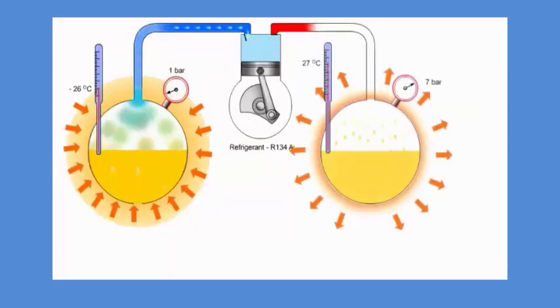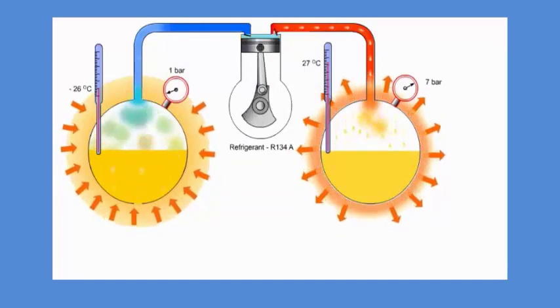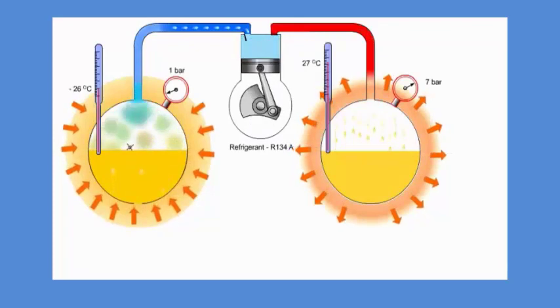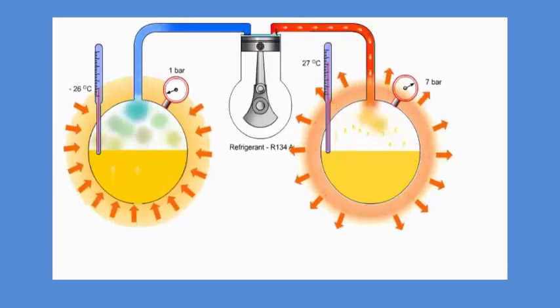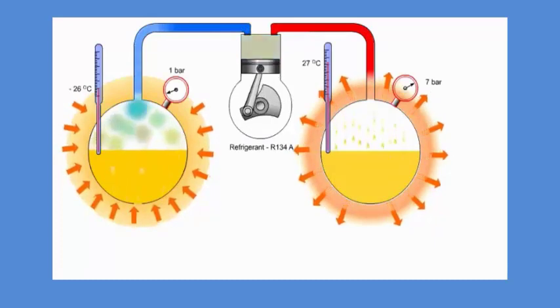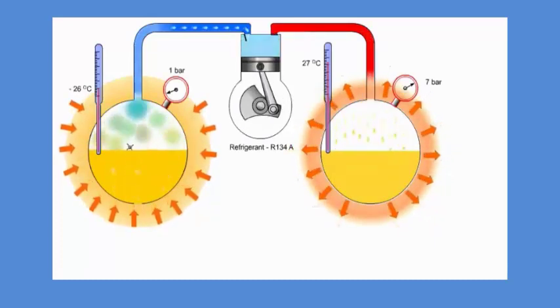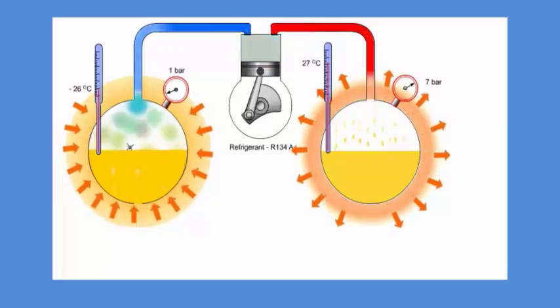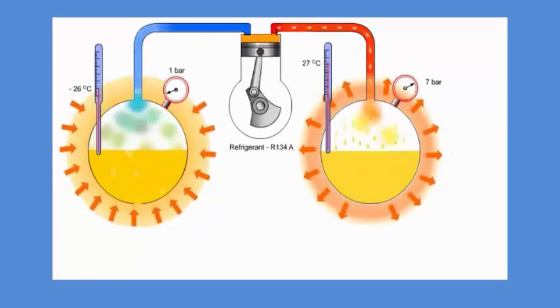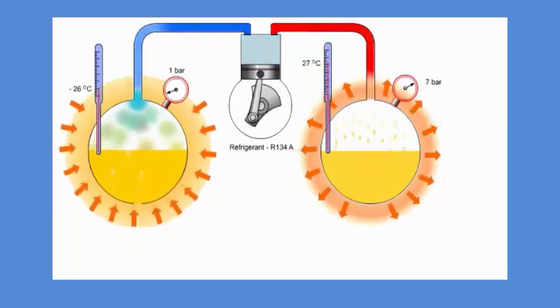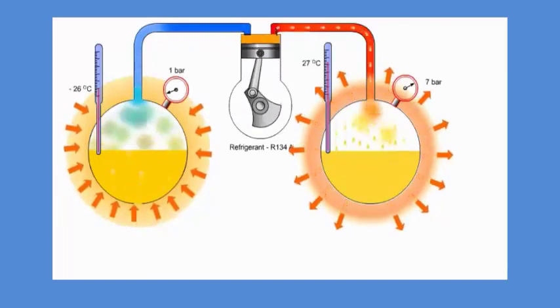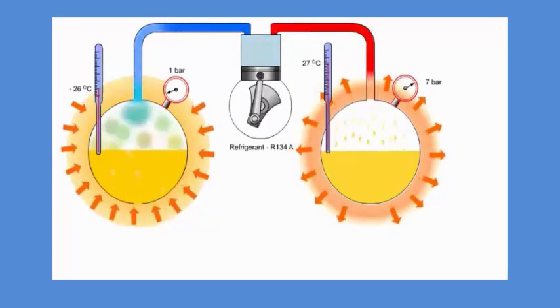You can again see the boiling refrigerant in the flask and the reciprocating compressor pumping away the refrigerant vapor. But now we supply an extra flask and connect it to the outlet of the compressor. This flask is accumulating the vapor from the compressor outlet. In this flask, the refrigerant is cooled down and will start to condensate when it comes into the flask, because the refrigerant is exposed to the relatively cold surface of the flask, which is again exposed to the ambient temperature of 21 degrees Celsius on the outside of the flask.